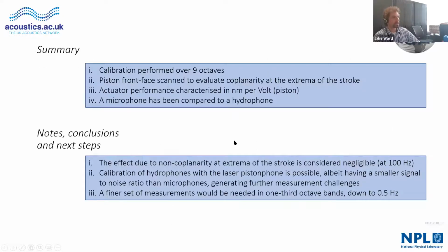So in summary, calibrations have been performed over 9 octaves. We scanned the front face to investigate coplanarity. We characterized the actuator in terms of nanometers per volt and compared it to a microphone. And we're looking forward to lots more work in this arena. So hopefully that's explained a little bit about low frequency calibration of hydrophones.